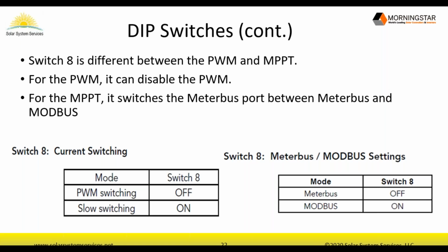So that's quite slow switching. So if for some reason you have a noise issue with the PWM, though I'd be surprised if your radio had one, you can go ahead and use that switch to disable that, essentially turning the PWM controller into a series regulator, which is more of just an on-off type regulator. And that would, again, at 1 second, you're not going to have any noise issues whatsoever.